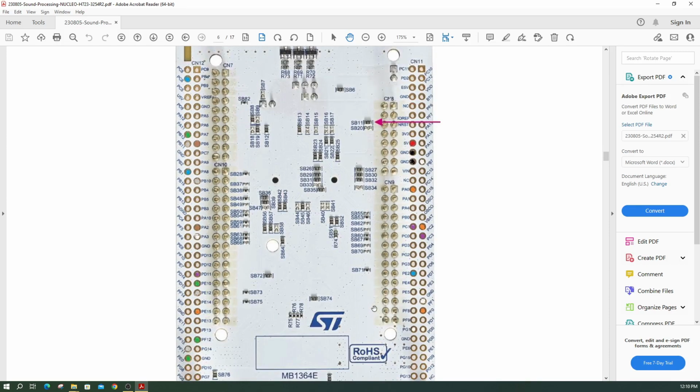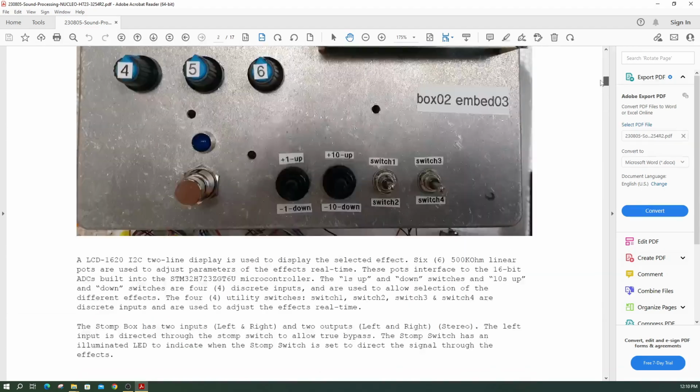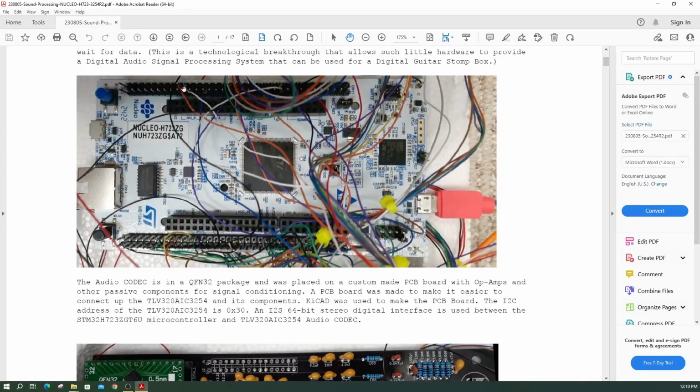I tried to use the connections that are already there on the one side that come with the board. I tried to use these, but there wasn't enough, so I added these headers. I soldered these onto the board because this has all the interfaces. See, this board isn't big enough. These headers here, I guess, were reserved more for our Arduino, and there weren't enough of them. The whole thing is not populated with all the pins with this device, but these outer ones are. So I got these headers and soldered them in.